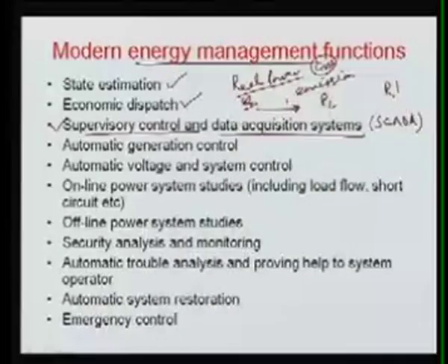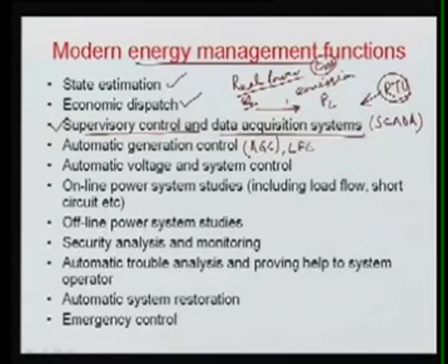Here the SCADA is nowadays very important. Any measuring unit like your RTU, that is a remote terminal unit, measures the data. At the same time, it can do some of the supervisory control as well, and other information it can send to the energy management function. Another function is called AGC, meaning automatic generation control. It is also known as load frequency control.